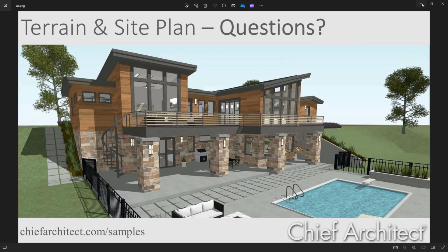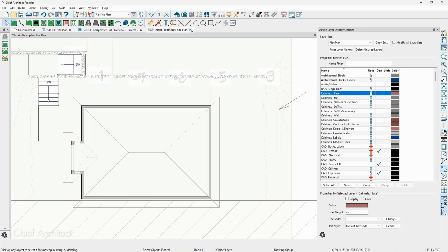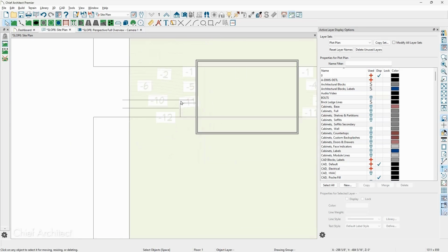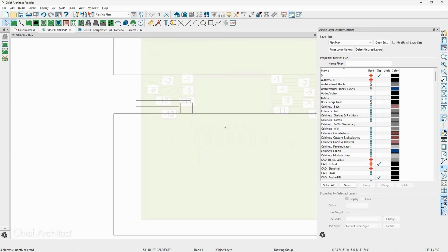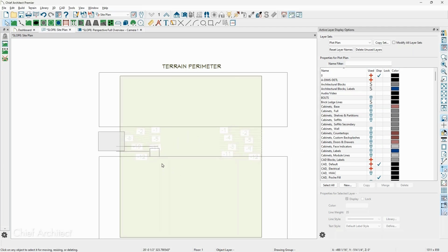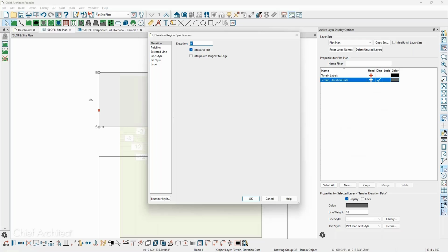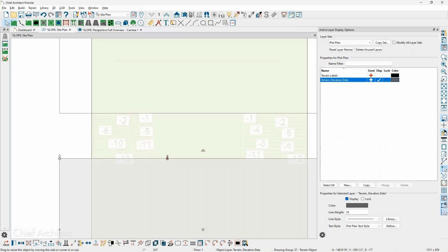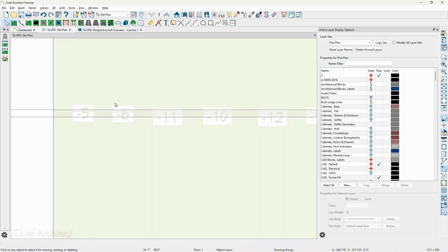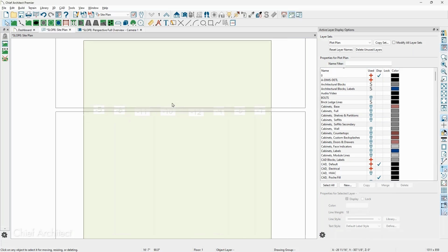Those are the dreaded shark fins that we refer to. Let me close a couple things here. So if I go into a sloping plan here, I'm going to delete my walls. So I've got a terrain perimeter, and in these scenarios, this upper one I think we set to 0 feet, and then this one's minus 12 feet. If these get very close together, you should get a pretty tight contour in here, right? Yes. Now, if those overlap in any way,